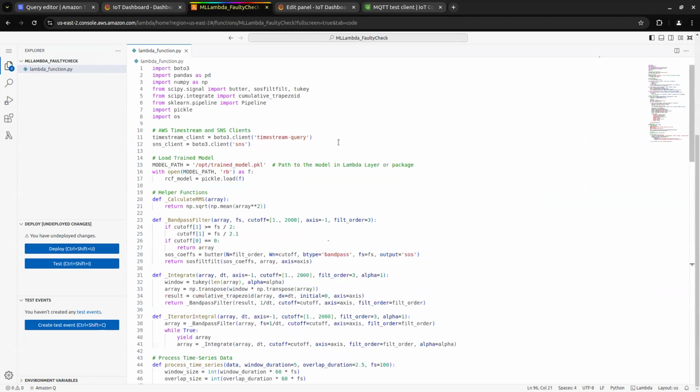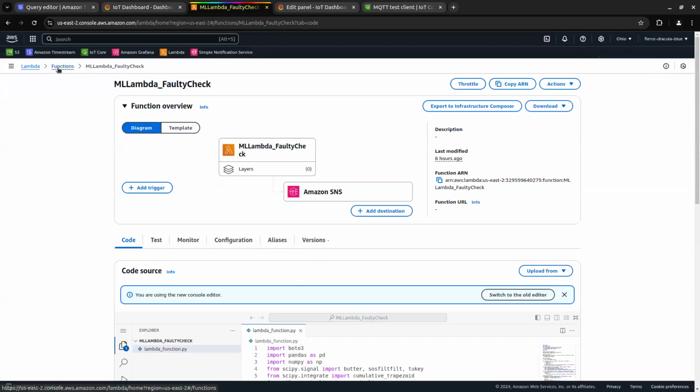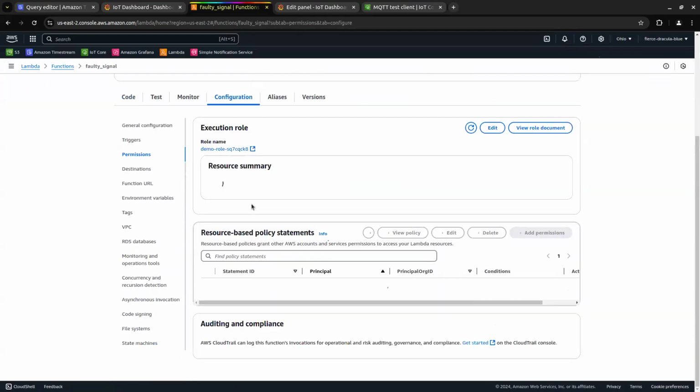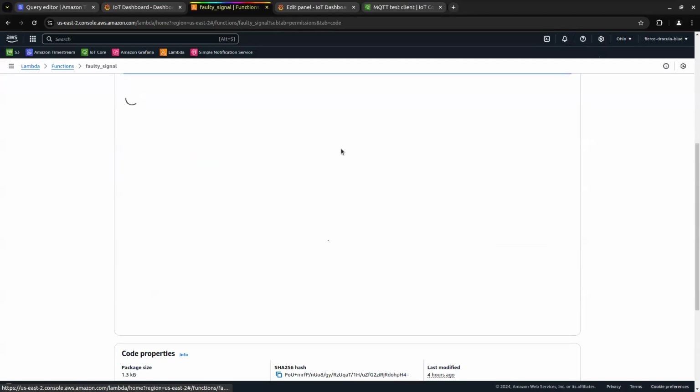So this block is responsible for sending email. In order to create a virtual faulty environment, because the machine learning model is trained on the machine having high temperature, high humidity, high gas resistance, poor air quality, and higher or lower velocity and displacement RMS, I have a sample example signal pre-programmed within the program.